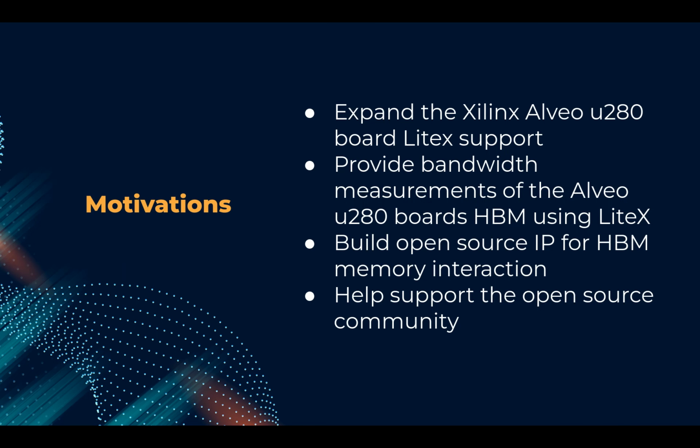First, I want to talk about the motivations for this high bandwidth memory project. Number one is to expand the Xilinx Alveo U280 board LiteTech support. One of the goals for this is to provide bandwidth measurements of the Alveo U280 boards. This means checking the throughput of the HBM under varied tests. Also, we want to expand the open source IP for HBM so other people can build upon our IP. This really helps support the open source community.